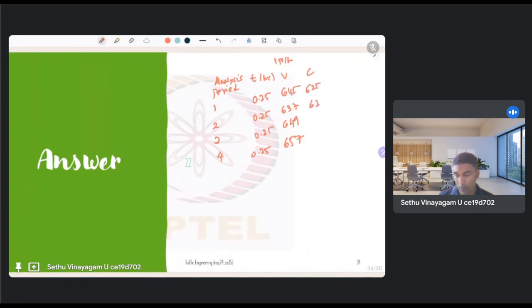This is not going to change across the periods. So whenever the demand is higher than the capacity, you are going to face increasing queue length, because that particular intersection is able to serve only 625 vehicles. If more vehicles are coming, those excess vehicles will have to wait, so they will form a queue.